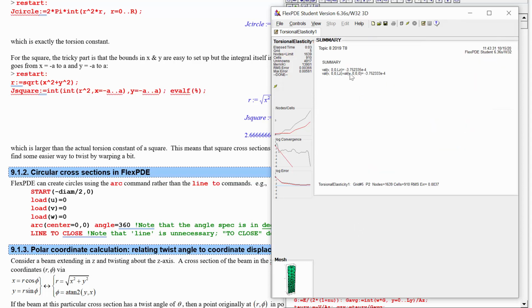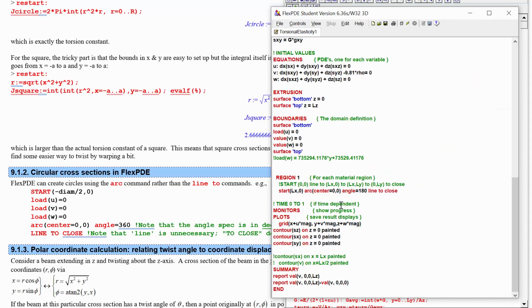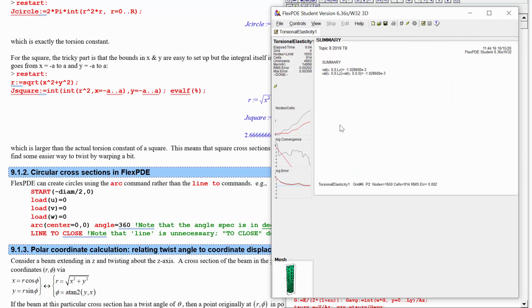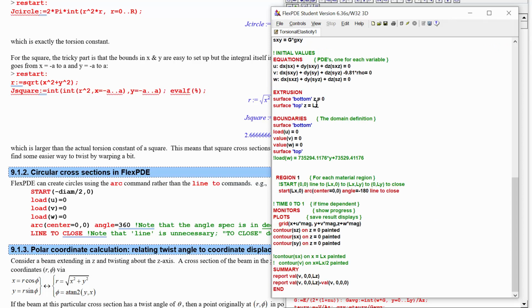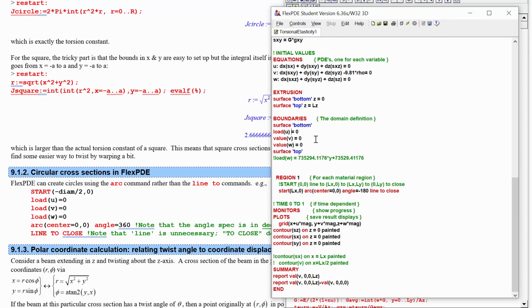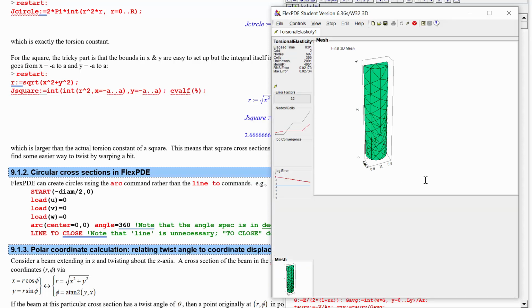It looks like we've got a displacement of 3.7 E minus 4. What if we did an angle of negative 180 degrees to have this thing upside down? It moves 1 E minus 3. It looks like it displaces, at least at the point that we're considering, more under its own weight if we put the arc part on the bottom rather than the top. And that's kind of interesting. Does it have to do with whether it was fixed in X at the back surface? Perhaps.